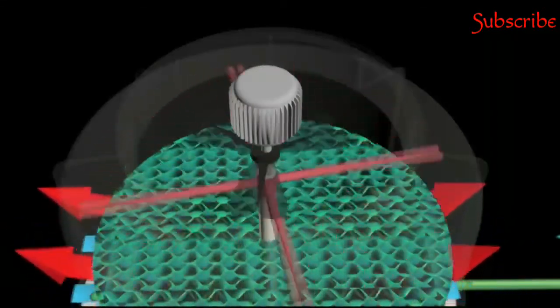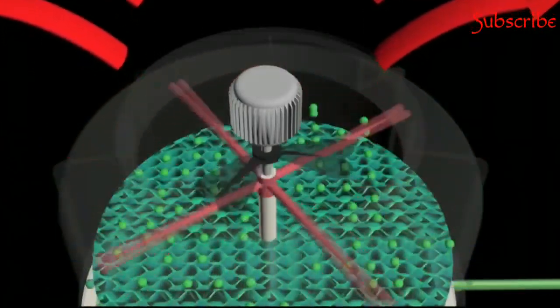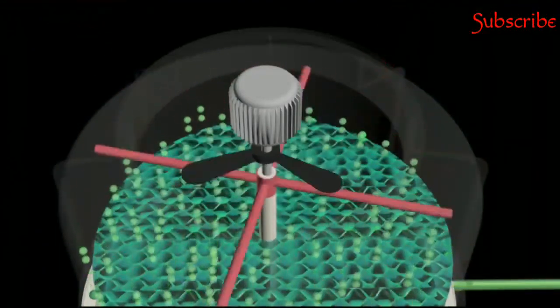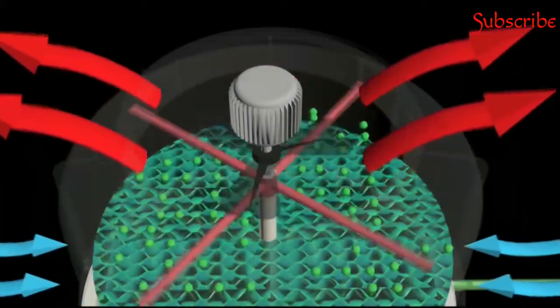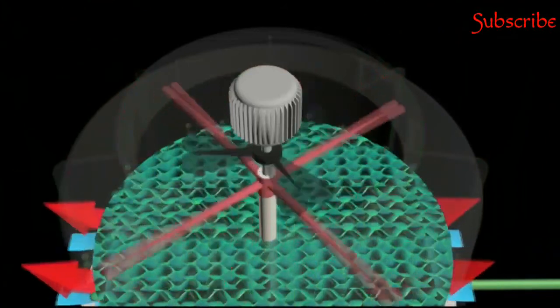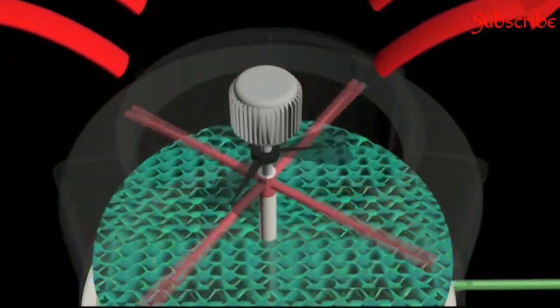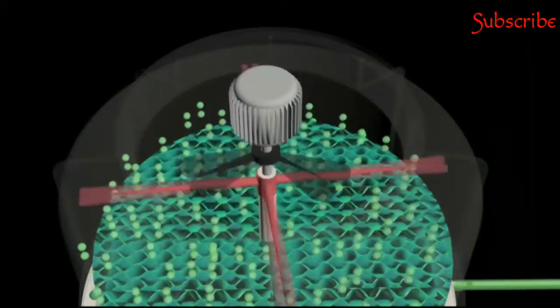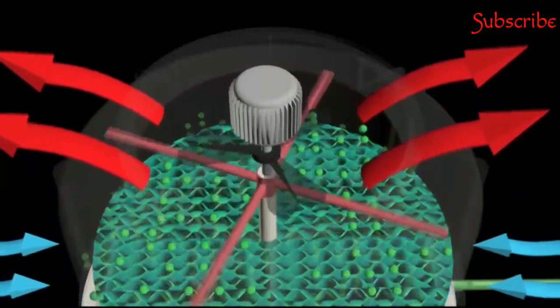This can delay the time and the heat can be absorbed more effectively by the surrounding air passing through the fins. Air through the fins is forced by a rotating fan on the sprinkler blade rotated by the motor. This fan rotates with its gusts upward. This will cause the air to move from the bottom to the top of the cooling tower, which is opposite to the flow of the condenser water.